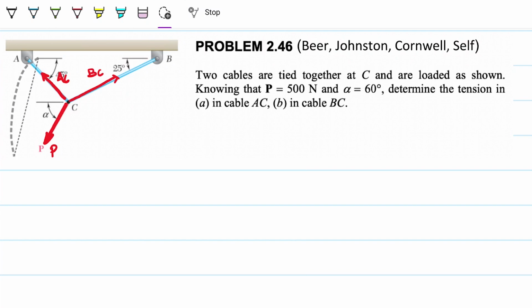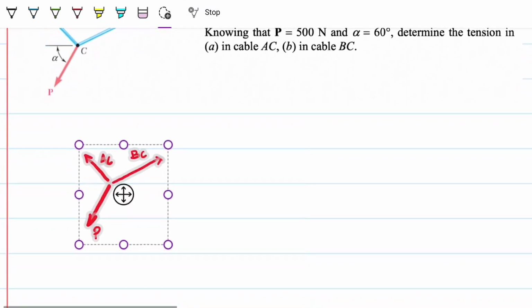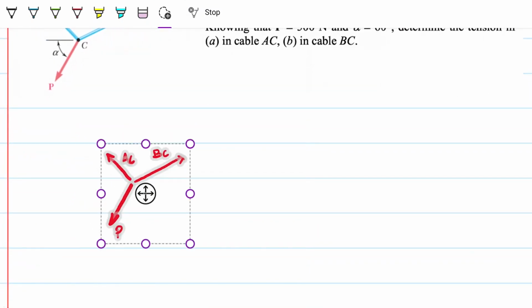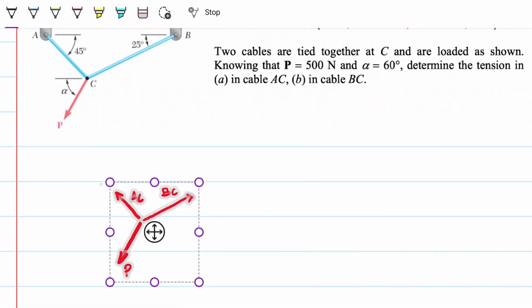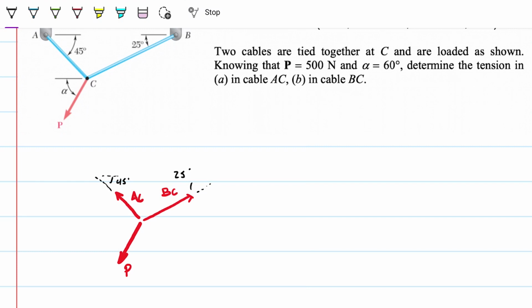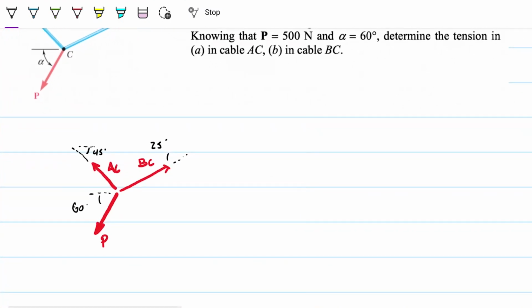As we always do, I'm going to copy this down here. I'm going to make an actual copy of it and note the angles that we have. Over here we have 45 degrees. Over here we have 25 degrees. And over here we have 60 degrees. Okay, and the way that we solve this is we create the force triangle.